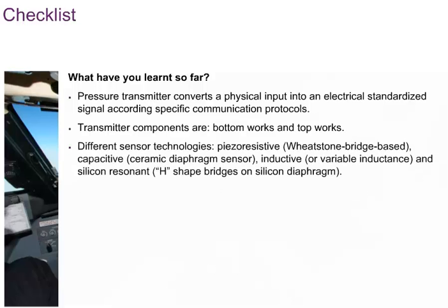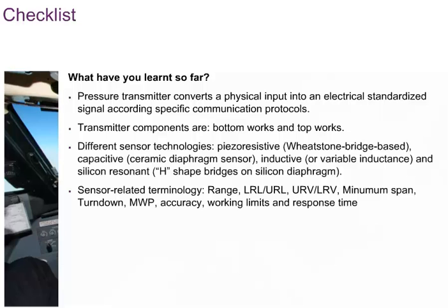Today's manufacturers exploit different sensor technologies. Piezoresistive, the Wheatstone bridge-based sensor, capacitive, ceramic diaphragm sensor, inductive or variable inductance, and silicon resonant, H-shaped bridges on a silicon diaphragm. Sensor-related terminology: range, LRL-URL, URV-LRV, minimum span, turn down, MWP, accuracy, working limits, and response time.